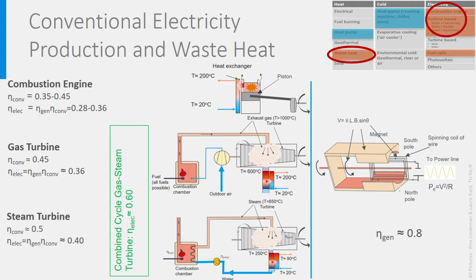Finally, a nuclear plant works exactly the same as a steam turbine, only the combustion chamber is replaced by a nuclear reactor and there is one heat exchanger more to make sure radioactive elements remain into the protective shell. The energy content of uranium is enormous and these nuclear plants deliver generally very large quantities of carbon-free electricity. Unfortunately, there is nuclear waste and risks due to radiation if control is lost on the reactor and after end of service life of the plant.